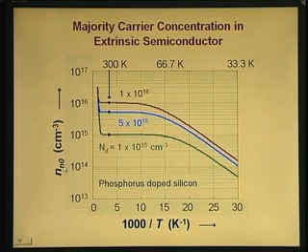So here this N stands for the electron concentration, this small n stands for the type of the semiconductor, that is it is an N-type semiconductor, and the 0 stands for the fact that the semiconductor is under equilibrium. We are going to discuss what equilibrium means later. So this is an equilibrium concentration of electrons in an N-type semiconductor, and this is also the majority carrier concentration because electrons are in a majority in an N-type semiconductor.